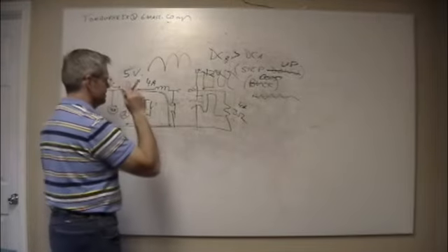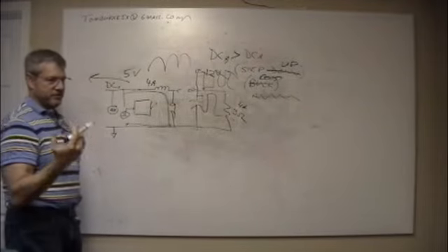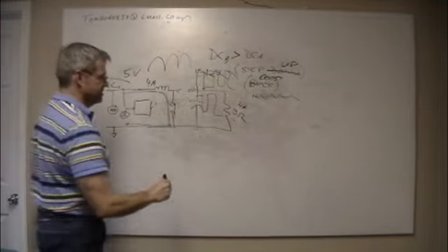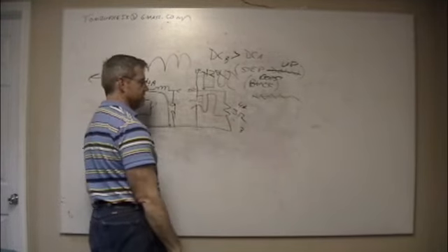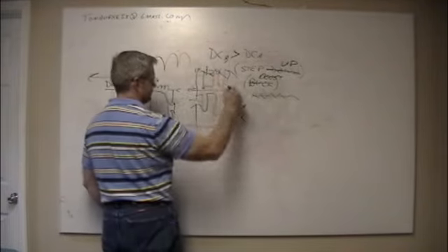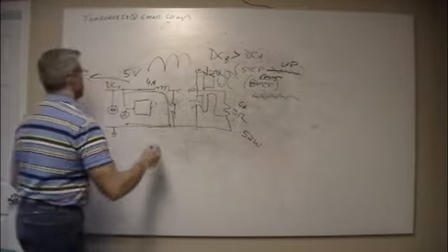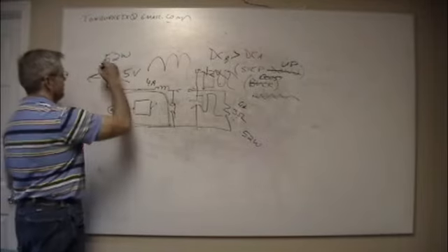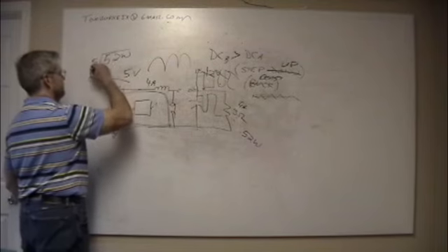But what I see is that to be able to do that on this side, it has to convert, and you have to conserve energy. So 12 times 3, P equals IV. IV is 4 times 13, which is 52 watts. That means I have to have 52 watts on this side. Divide, V equals... P equals IV. Divide by 5, that's 10 amps over here.